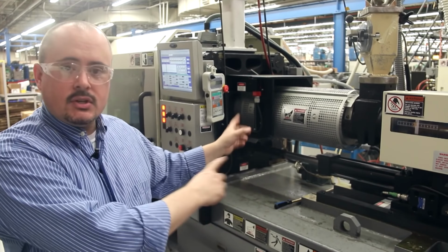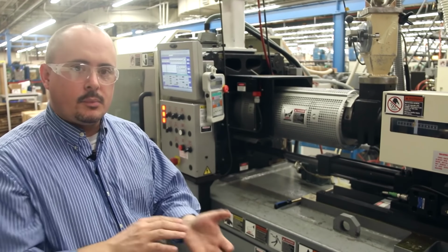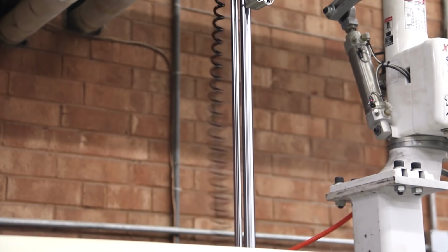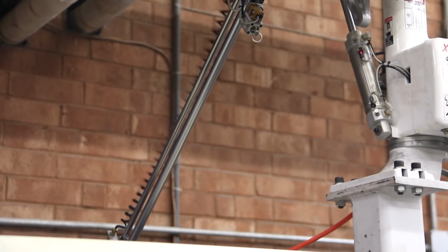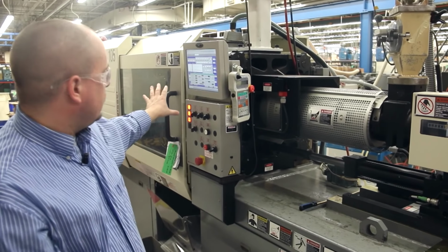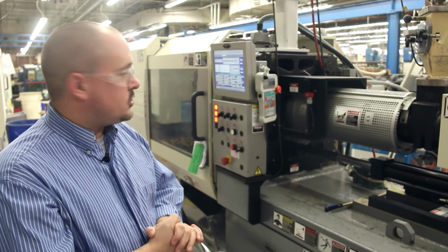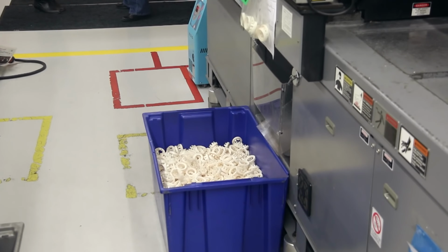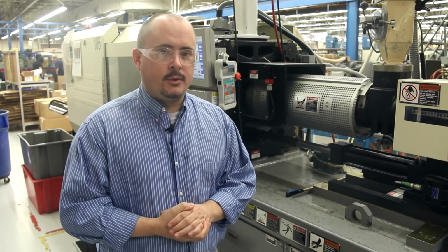So as it's injected through, the controller that you see here will regulate the pressures, the times, the temperatures, and all the other variables inside of this to make an acceptable part for our customers. As that goes through and as that completes, it'll form into a solid form inside the mold again. Once that's done, it'll eject the parts out and they'll be ready for shipment and or assembly. That's how molding works in the Thompson department here in Elizabethtown, North Carolina. Thanks for watching.